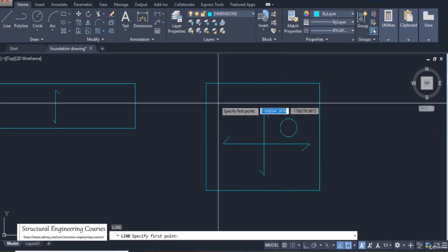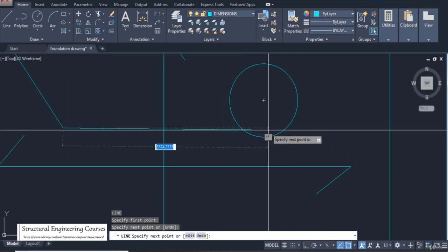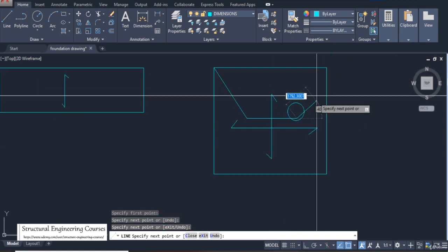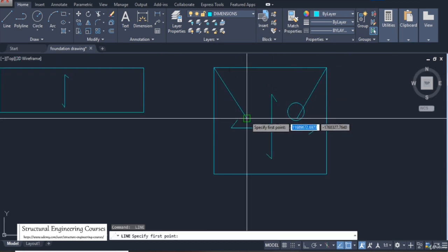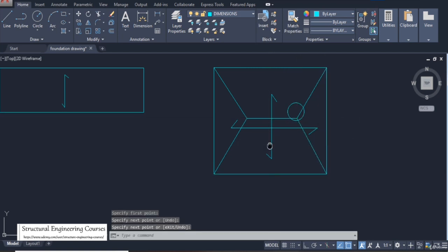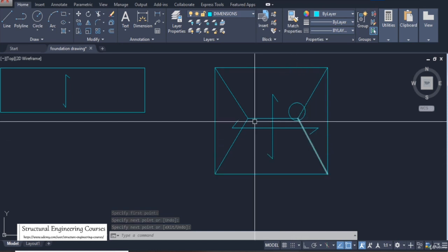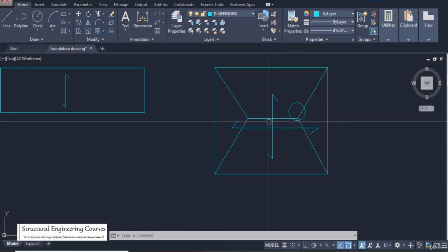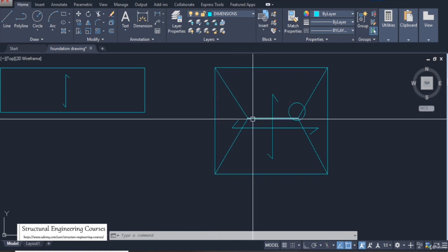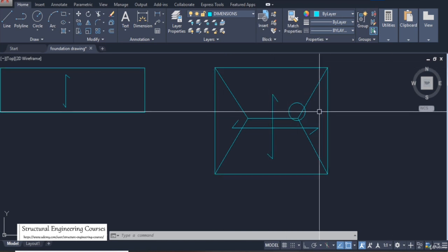So for that, basically, yield line diagrams can be drawn here, like this. So the loading on this particular beam shall be the area of this trapezium. The loading on this particular beam shall be the area of this triangle into the loading that is acting on it. Similarly for this beam and similarly for this beam.